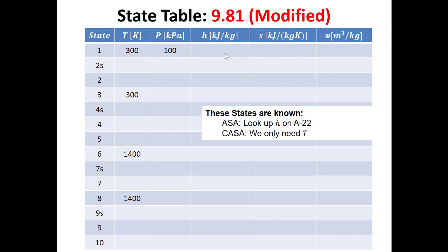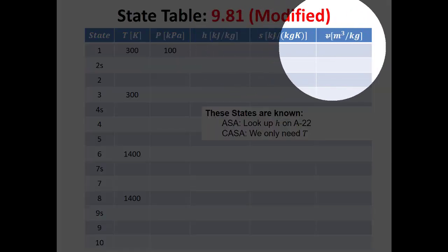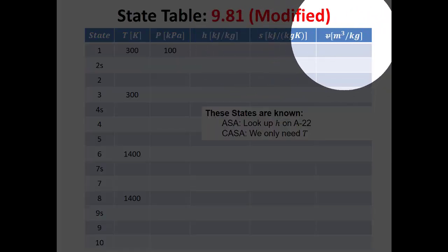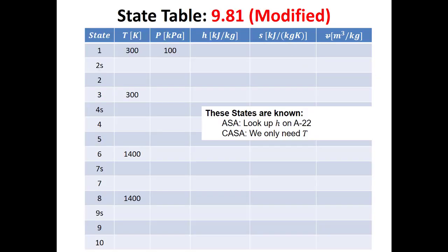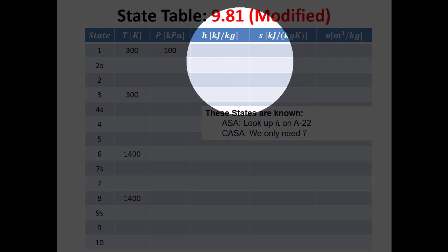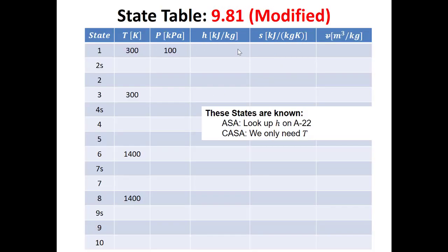and because it's a series of open systems where I know the pressure ratios, instead of the specific volume, which I don't think I'm ever going to need in this problem, I would write down probably Pr here and find the reduced pressures at all the states. Everywhere where I know the temperatures, I can go through and get h, and I could get Pr.